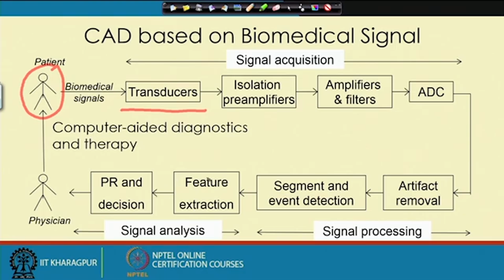But here we would be more interested in the transducers which give us electrical output, and then we will play with those electrical signals. And as we are connecting the human subject with the electrical signal, there is a need of an isolation, so that even by mistake the electrical potential of the instrument is not injected back to the patient. We need to have an isolation preamplifier.